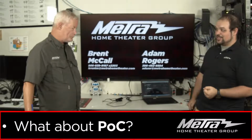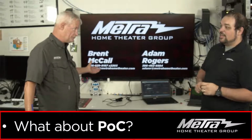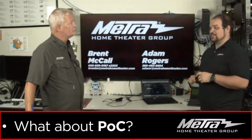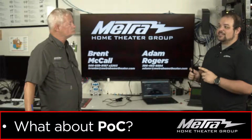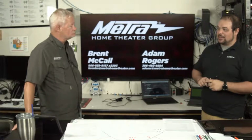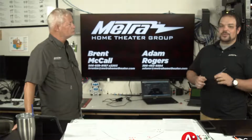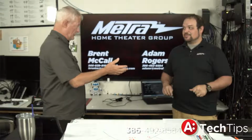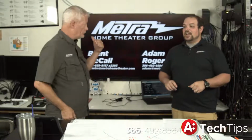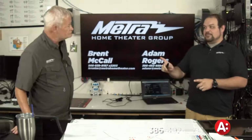So, here's the difference. Power over cable goes way back in our world to the early days of satellite. Now, here's what's interesting about this. The power over cable isn't so much about power over coax. This is actually still power over Ethernet. However, it's used by HDBaseT. So the biggest difference is that other alternatives to HDBaseT, the less expensive ones, also use a POC format.